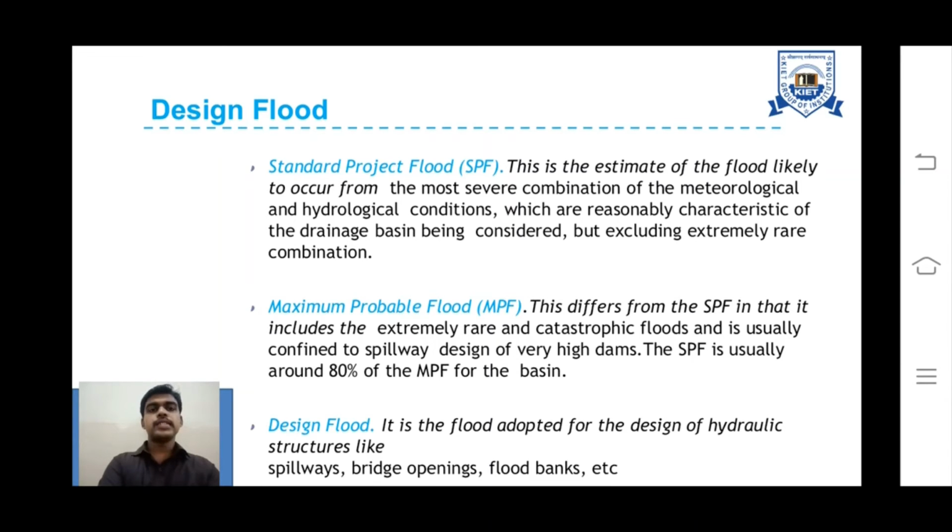Then finally comes the design flood. By considering the above two, that is the standard project flood as well as the maximum probable flood, we are designing the design flood, that is, the flood adopted for the design of the hydraulic structure. Here come the spillways, bridge openings, flood banks and other hydraulic and water body structures. So these are all very important things we have to keep in mind. Standard project flood, maximum probable flood. By considering these, we are going to design hydraulic structures like spillways, bridge openings and flood banks.